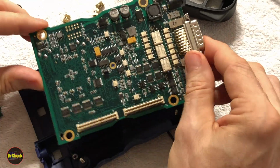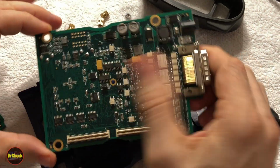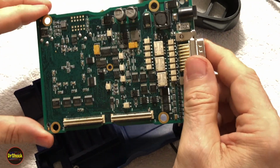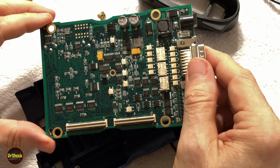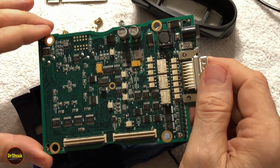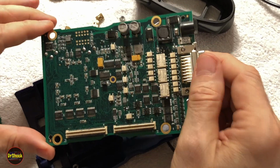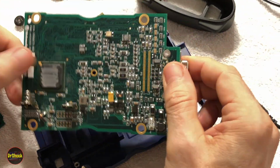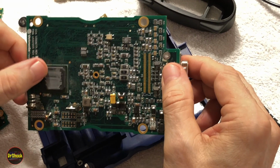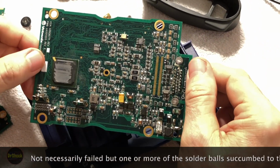So what could you do to repair it? Well, you might want to take the time to go check all the coils, diodes, and resistors and make sure nothing's open circuit there or shorted to ground. It's not going to be a problem with any of these relays or any of these buffers that's causing this kind of problem, but you can go through and do the basics and check for any shorts to ground. But it's most likely going to be that this chip right here has failed. And it's not like you can replace it, right? Because you have no way to program it.